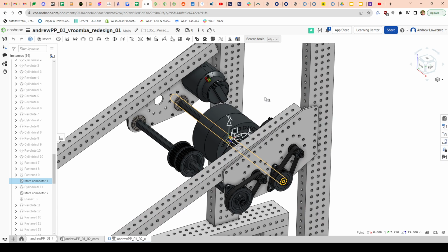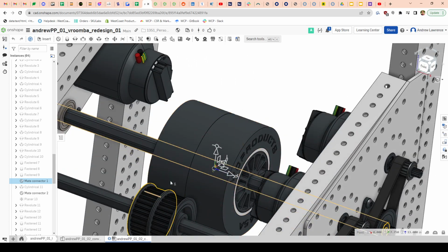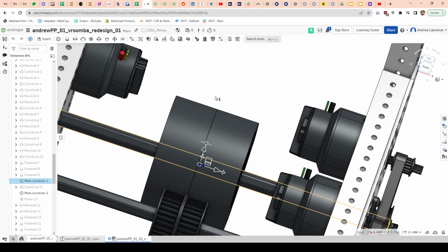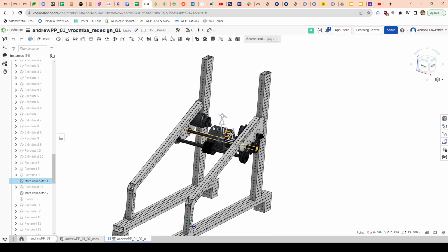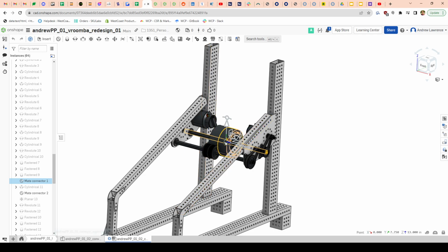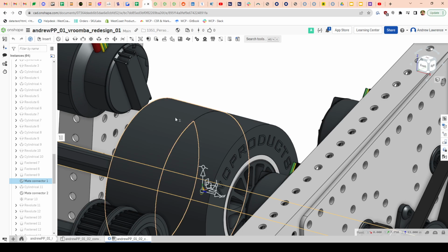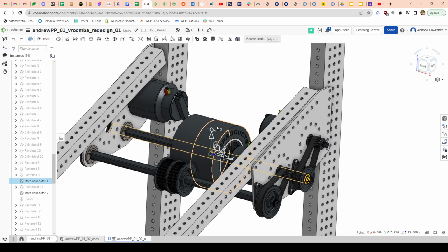So at some point, I ran into the issue of wanting to put this wheel at the very center, the inside face of this wheel on the center line. But there is no center line because there's no planes in assembly. So in a Part Studio, I can model this on the right plane so that it's contacting the center. So I could have one to the right of center and one to the left of center, which is what I wanted. I wanted to use 2 wheels. But there's no planes here. There's nothing I could have done.